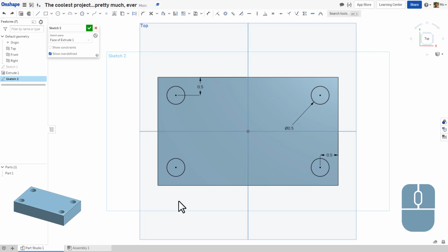Now, in different CAD programs, right, be they SolidWorks or Autodesk Inventor or whatever, the color coding scheme is different. But we know that there is a difference between the unconstrained color of lines and the constrained color of lines. And this is where we want to be for every one of our sketches, right? This is what defines a professional sketch from an amateur sketch. Okay, so now that we are fully constrained and all of our holes are ready to be drilled, let's click that green checkbox.